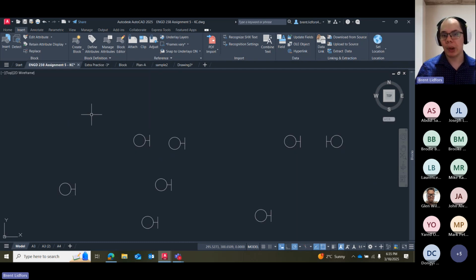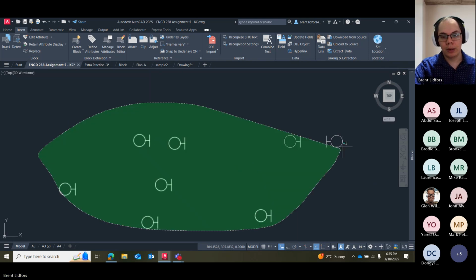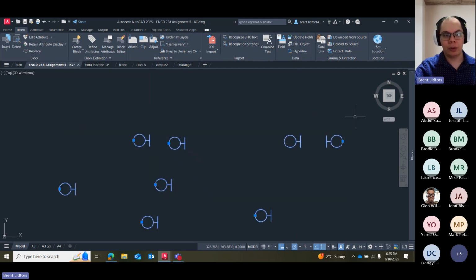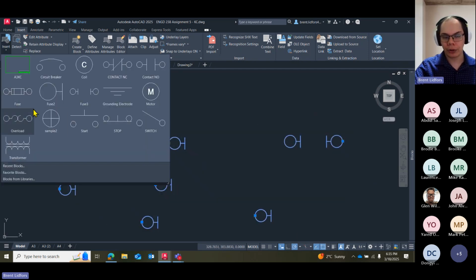If I try to make a block under the name of a block that exists, then I'm redefining the blocks that exist on my drawing already. Okay. So that's again 2 different ways of saying that blocks are associated with their own name. If you try to use the same name twice, it's going to cross its wires and then use a different block definition. Okay.